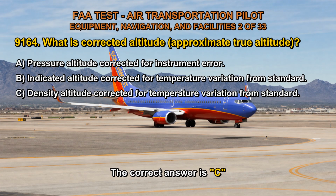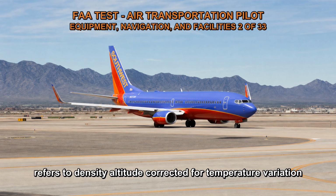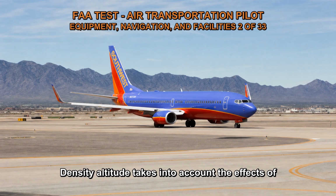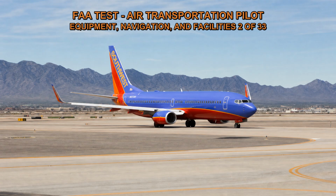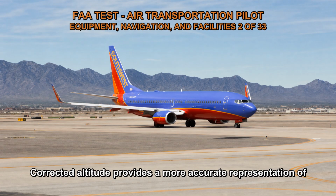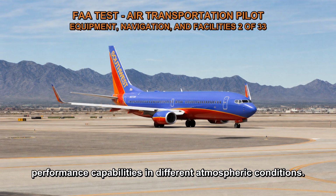The correct answer is C. Corrected altitude, also known as approximate true altitude, refers to density altitude corrected for temperature variation from standard. Density altitude takes into account the effects of temperature on air density, which in turn affects aircraft performance. Corrected altitude provides a more accurate representation of an aircraft's true altitude in relation to its performance capabilities in different atmospheric conditions.